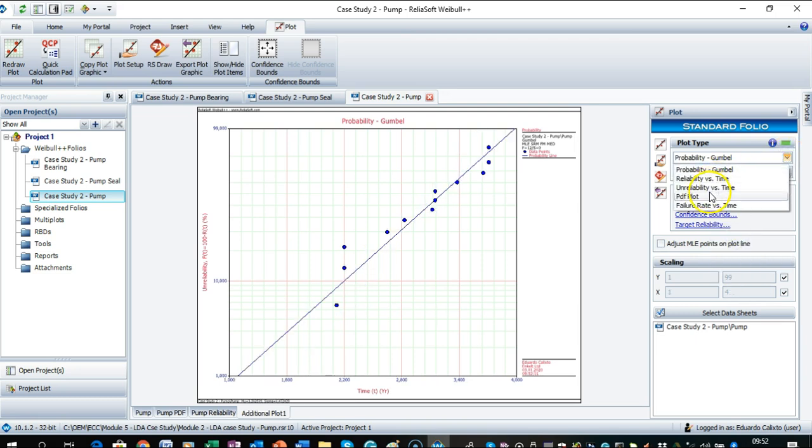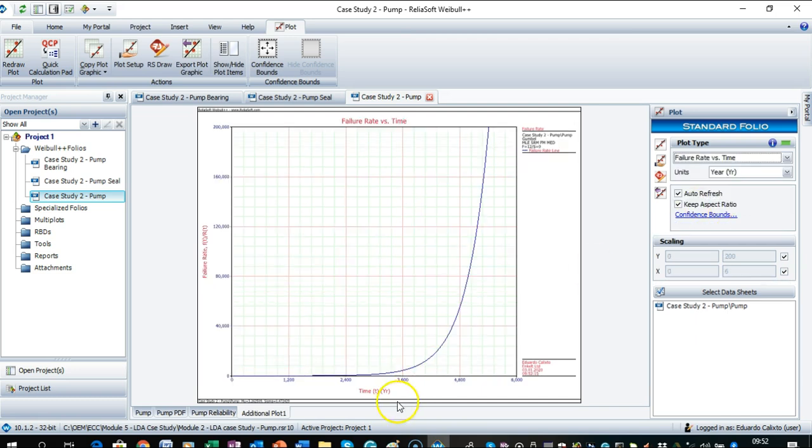And then let's take a look at the failure rate. That's a very interesting, important issue. So if I look at the failure rate, I see that considering the seal characteristic, I need to make some inspection before 2 years. Here we see that the failure rate at 1.2 is still lower, and then the failure rate started to increase after 2 years, let's say 3, 4.